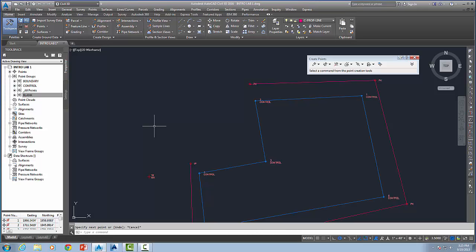And we have 2 bearings that we can use to establish this. We don't really have distances, although if you look at the plat, you have both bearings and distance. Actually, let's see, the plat does have bearings and distances. So you could use 2 distances to establish it. You could use 2 bearings to establish it. You could use a bearing and a distance from one of those points to establish it. And all of those solutions would give you slightly different answers.